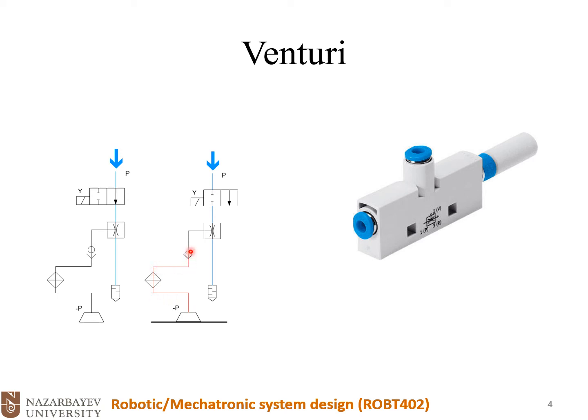Okay, now you see that we have a closed circuit. We don't have now any leakage of the air to the Venturi or to the atmosphere. Why don't we have any leakage of the air to the atmosphere? Because after we managed to suck the part by the suction cup, we could also close the directional valve.